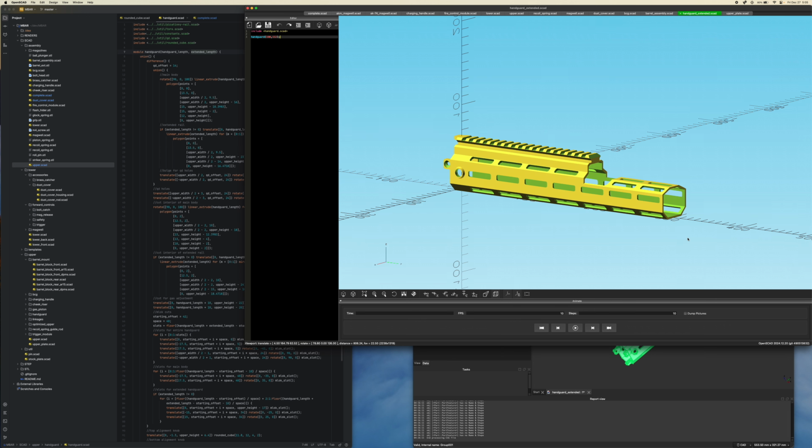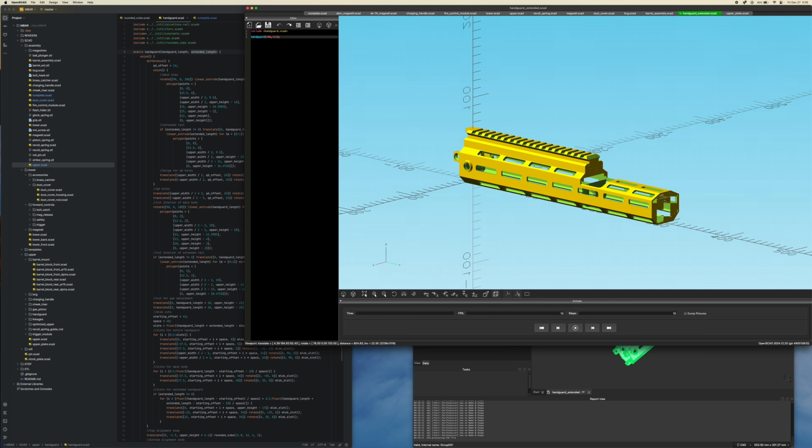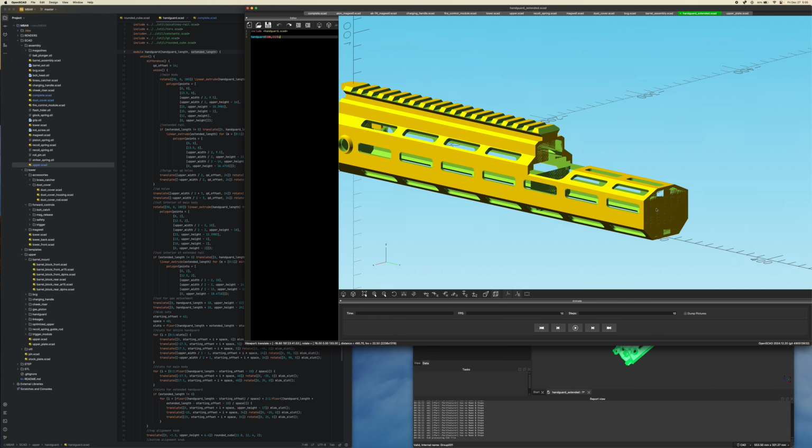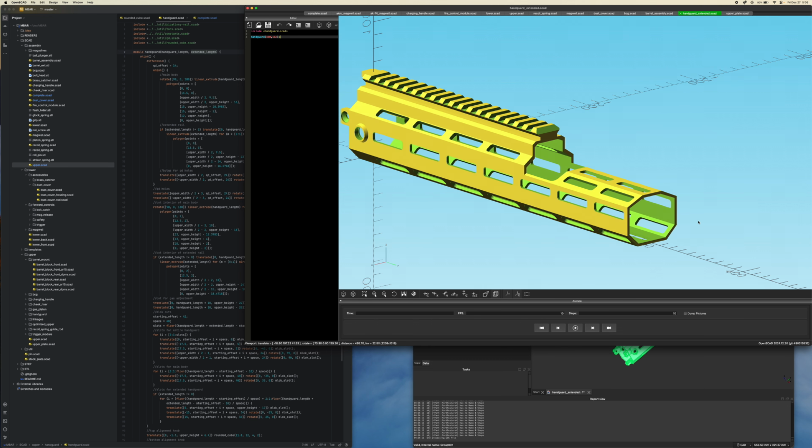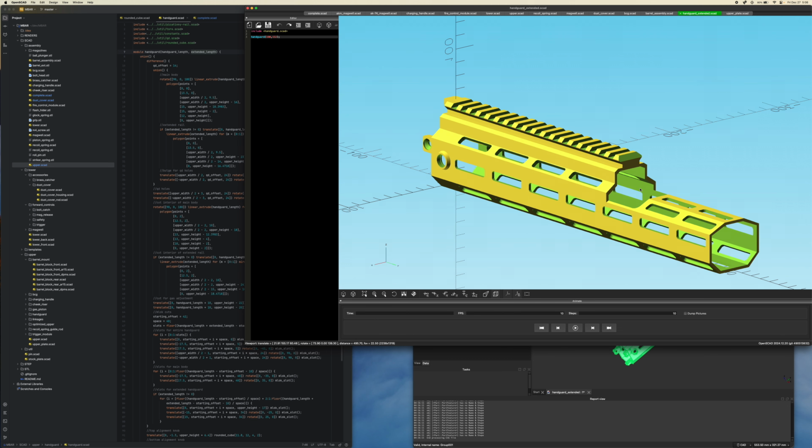First thing you notice is when I did the preview here, you'll see these fuzzy lines over here. This is something called Z-fighting. If you want to get rid of this, you just have to make the difference you're using to cut it open larger by like 0.01 millimeters or something like that. But I usually don't bother with that since once you click render, it goes away. I don't really use the preview for much at all.